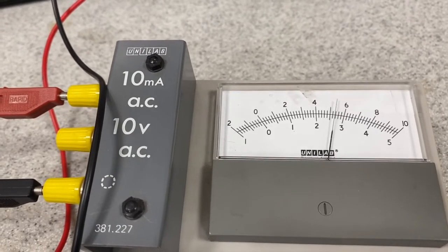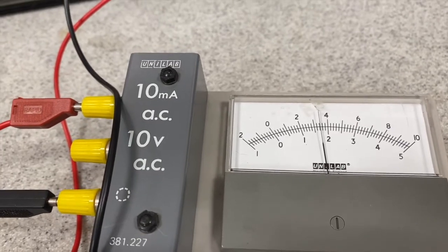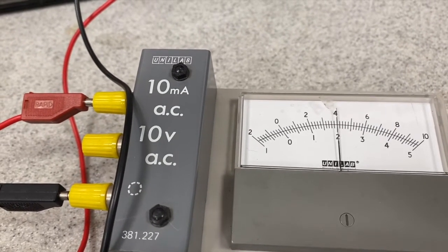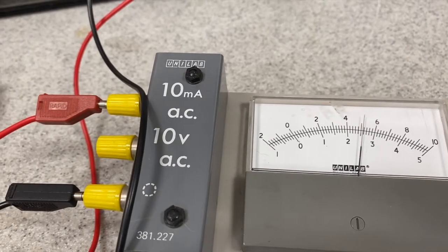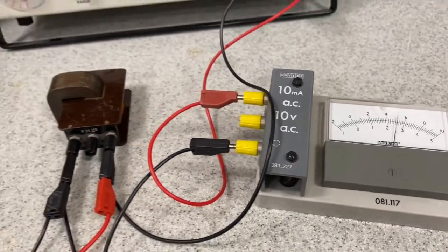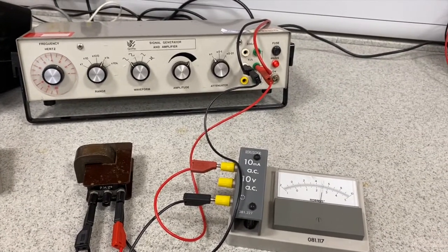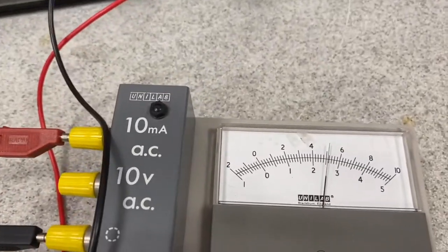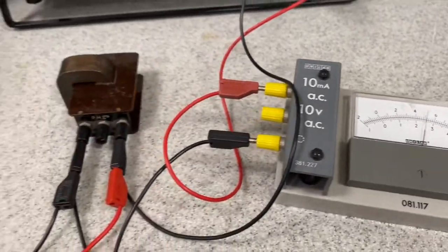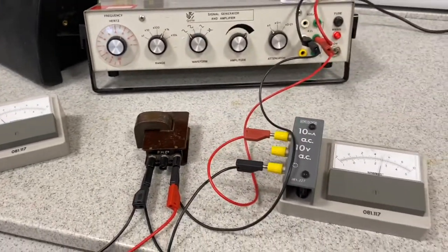Higher frequencies, lower currents. And again, we can make some measurements of frequency and current and measure the inductive reactance of our inductor there. Let's do that. Set it at 4000 hertz, and we're going to make a note of that current. And we're also going to measure the RMS voltage across our inductor there.